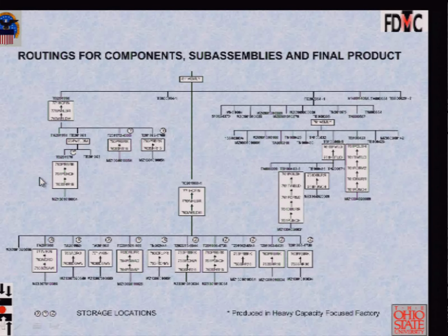But looking at what Toyota has proven, when you ask, why can't I create focused areas, one for this sub-assembly, one for this sub-assembly, and one for this sub-assembly, by the time you look at the true utilization of the equipment, what the guys doing group technology and then later the guys at Toyota found out is that through right sizing, through equipment utilization improvement studies, they could use existing equipment and create separate focus factories to make these sub-assemblies.